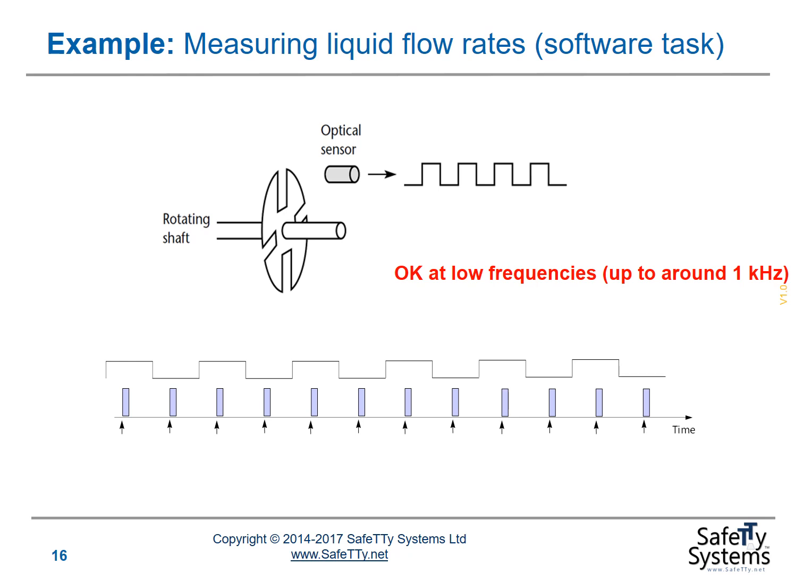In a real-world design, the waveform would not be perfectly square. We'd see some attenuation of the signal. We would see some changes to the shape of the signal as a result of cable effects, capacitance in the cable, etc. We'd have a filtered version of that waveform. We'd have to decide when we were going to sample the waveform. We'd have to sample at quite a high rate to be comfortable and ensure that we had not missed any pulses.